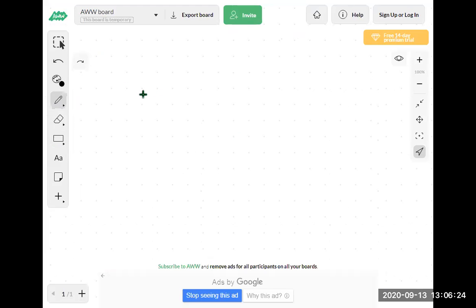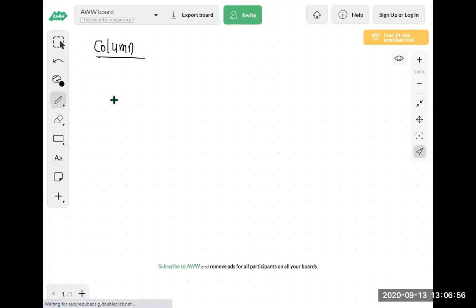So, in the last lecture, we have seen the design of compression members, single angle and double angle compression members. The procedure we have seen. So, the next part of unit number 4: the first part is the compression member and the second part of unit number 4 is column. Now we have to design the column. Compression member means single angle strut and double angle strut we have designed. Now in column, we are designing the I section and channel section.